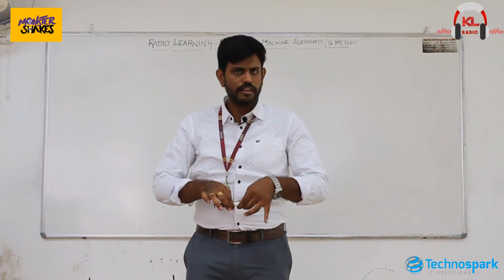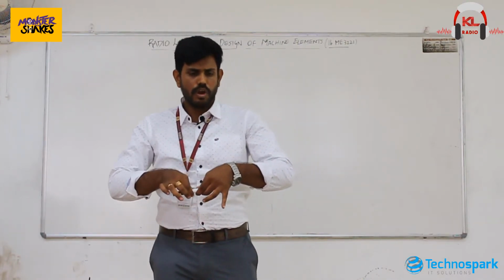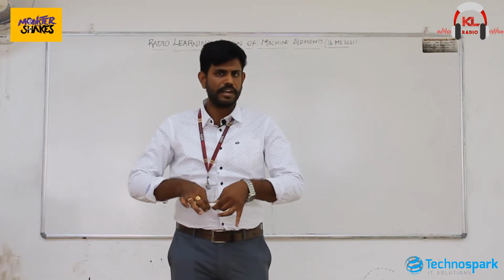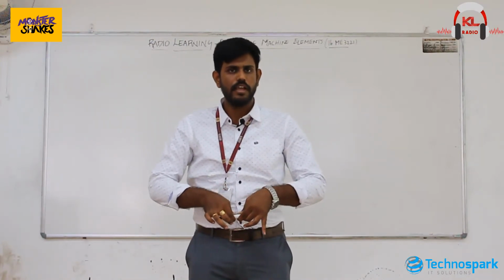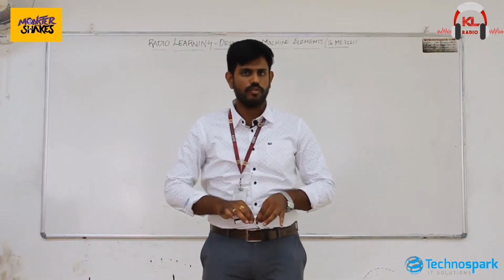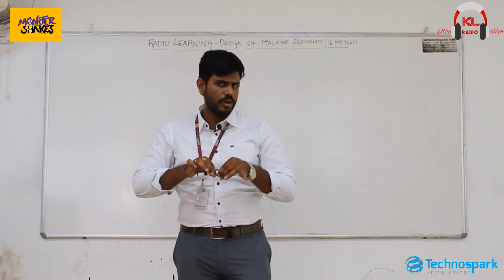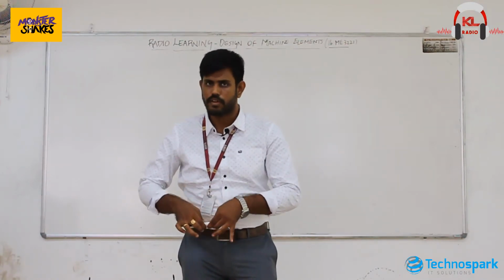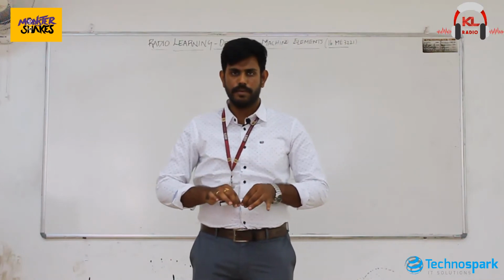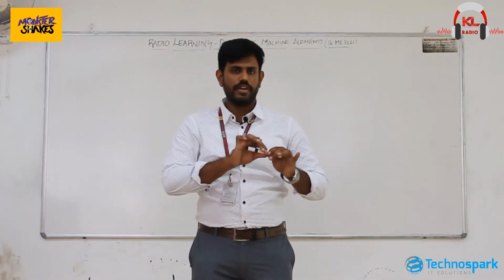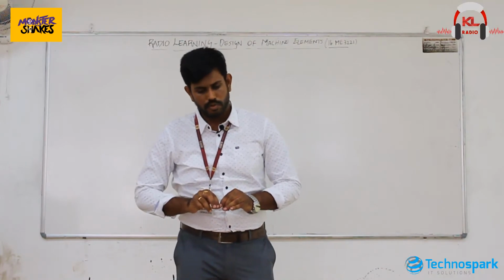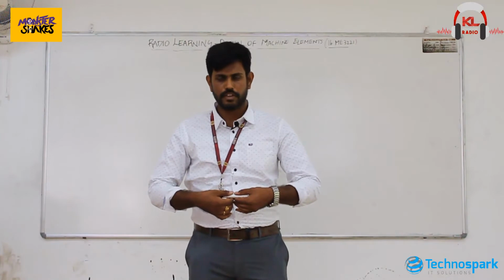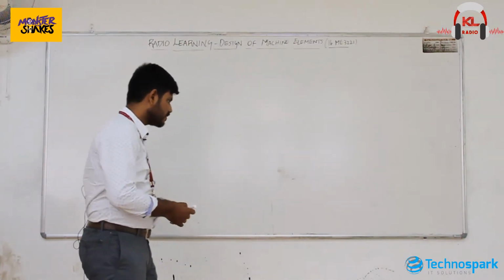Now you can observe that in fatigue loading, the failure of the object or particular mechanical element is not predictable. Actually it's unpredictable. It may fail before the yield point also. For that purpose, we don't consider the yield strength of the material directly in the design for fatigue loading. We will be considering the endurance limit as the limit for design for fatigue loading. We will be looking at different fatigue loadings, because fatigue loading is also of two types actually. So we will be looking at those things.